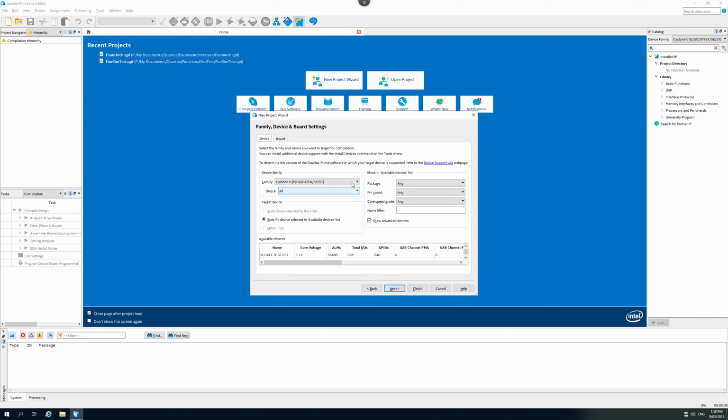Now here, the Cyclone 5 is quite a complicated FPGA. You can follow the same steps that I did and choose the Cyclone 5 and you'll see a much more complicated, the architecture itself isn't that much more complicated, but the insides of an individual logic element is. Also, as there are very many more logic array blocks, you'll find that when you go to view things, you sometimes just get overwhelmed with the large numbers of logic array blocks you have. So we're instead going to choose this Max2.